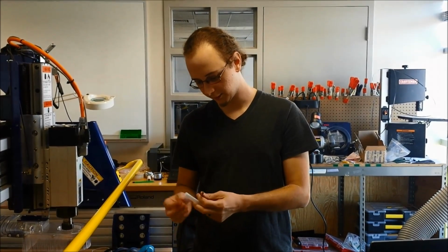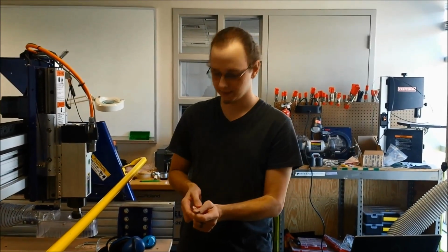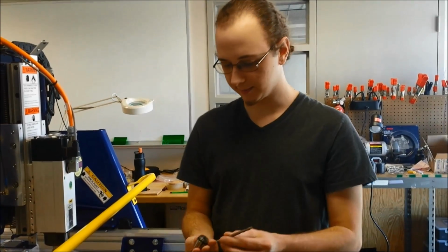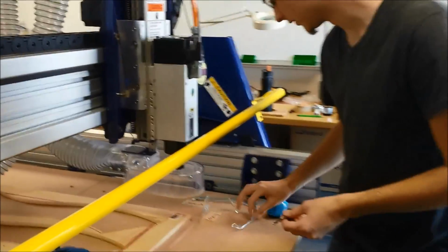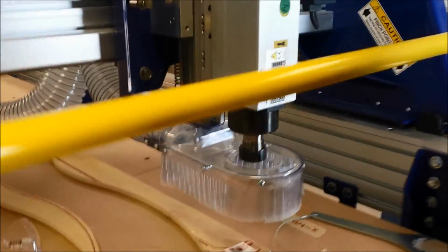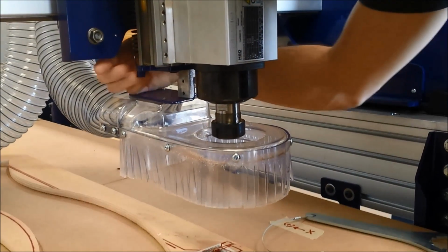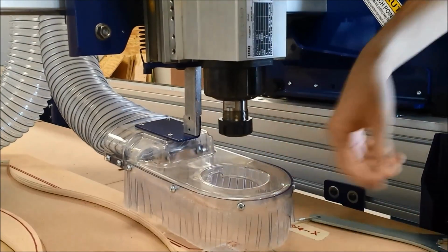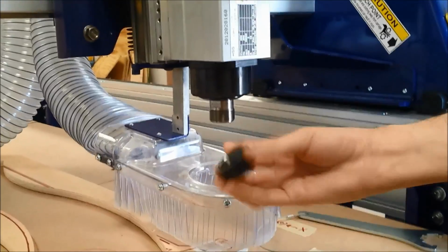And so we have this end mill. We need to get the appropriate size collet. So this is a 1/4 inch collet that we'll be using. The way we're going to use this is we're going to put this actually inside the spindle. So I'm going to move some of this stuff so you can see what I'm doing here. The spindle has this shroud around it, and we're going to have to remove that. So in the back there's a little thumb screw right where my hand is, and you can loosen that and it drops down, and that allows you to access the spindle head. So we take this off,